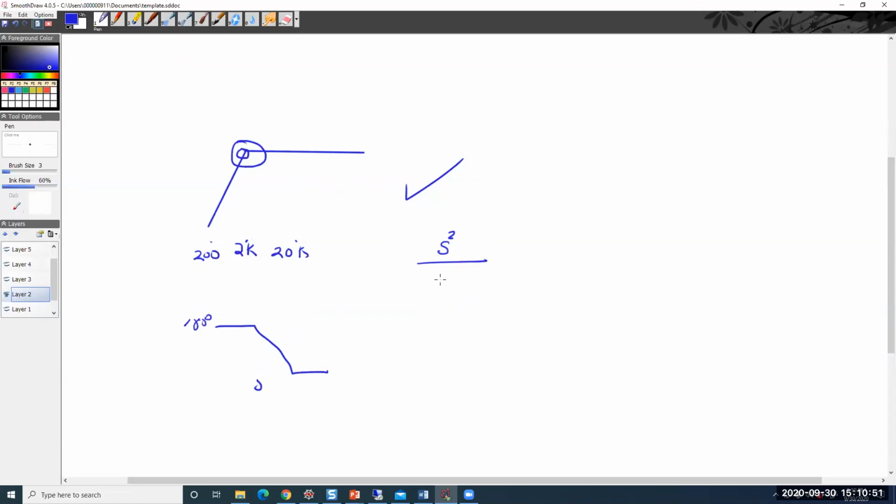However, you could have a repeated pole, where let's call that A, and that's A divided by 10, and 10 times A. You could have a version where the poles are separated by 100, where this would be A divided by 10, and this would be B divided by 10, times 10. It just pushes the curve out.